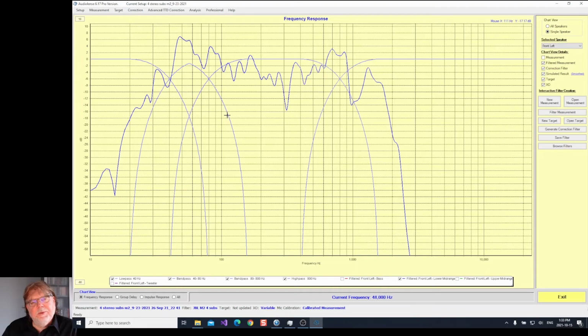And, just to speak about this a little bit more, when we go ahead and start convolving these minimum phase responses with the crossover, the response of this sub that we're seeing here is now going to be encapsulated in the linear phase crossover. And the reason why we're using linear phase crossovers is because they sum together perfectly in both the frequency and the time domain. And there's very few crossovers, especially passive crossovers, that really do that.